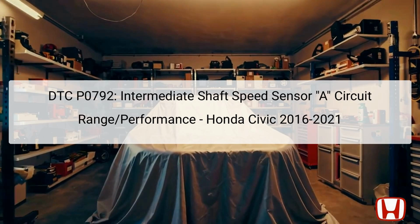DTC P0792 indicates an issue with the intermediate shaft speed sensor A circuit in the Honda Civic models from 2016 through 2021. This sensor plays a crucial role in monitoring the speed of the engine's intermediate shaft, which affects the transmission's performance and efficiency. When the system detects that the signal range or performance of this sensor is not within acceptable limits, it triggers the DTC P0792.